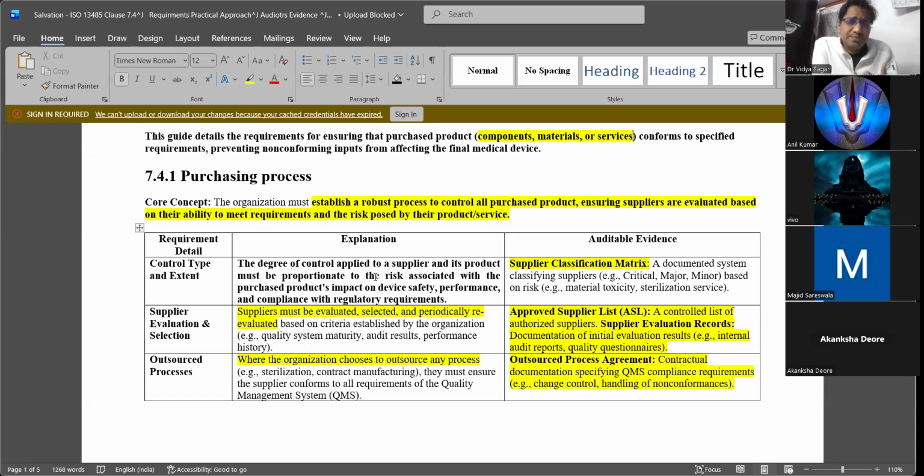Some of the components, basically in implants, implantable medical devices, could be very costly. Why test them and destroy them? You can just manage it based on the specification, orders and all that stuff. But that is strictly prohibited by ISO 13485 clause 7.4. You need to test the materials.